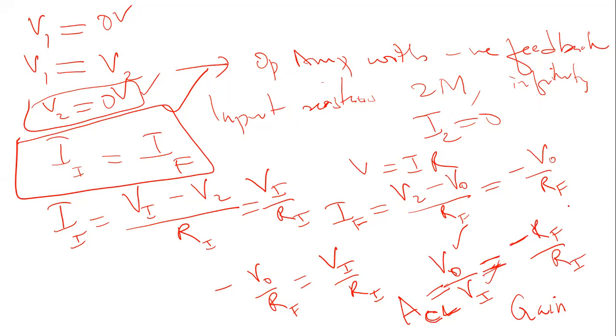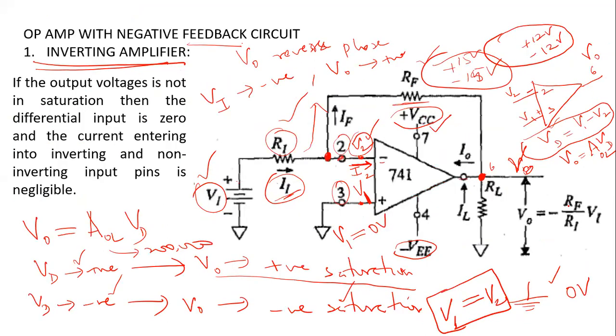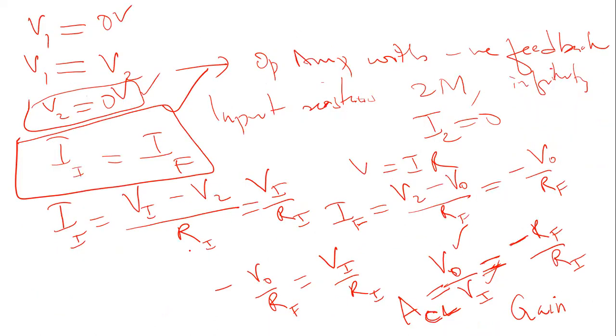What a very interesting conclusion we can see here from this calculation is that this operational amplifier, without your feedback circuit, has a gain that is more or less fixed at 200,000, right? But once you have this feedback resistor and one input resistor, the gain of your amplifier is now negative of the ratio of the feedback resistor upon the input resistance.